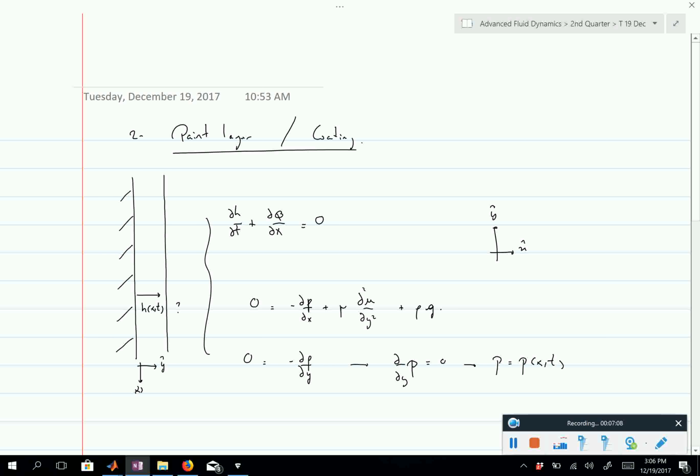Now, in that case, what is the pressure? I think you already answered the question, but in that case, what is the pressure inside of the film? Why is it atmospheric pressure? What concept do you use to say that it's atmospheric pressure everywhere? Actually, you're right. This is the one thing which I didn't say. When you say the pressure is the same, we are assuming that the curvature is going to be really small.